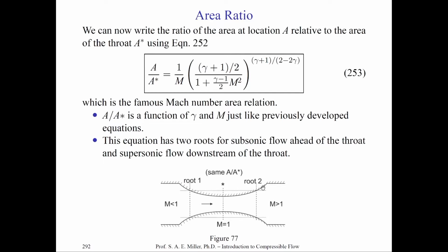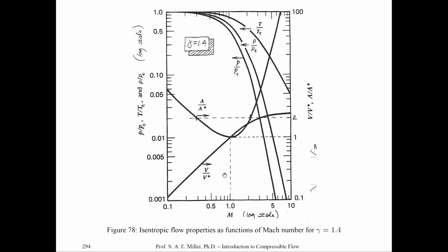Right? It's dependent on the particular cross-sectional area as a function of x. So A is a function of x. A over A sup star will always be 1 at the throat, that's unity, and we're letting it grow before and after the choking point. Now, the dashed line on the choked or transonic or critical condition corresponds to this particular dashed line on figure 78. So I'm taking the physical problem and transforming it to the problem of the graphs. It's a transformation or mapping.